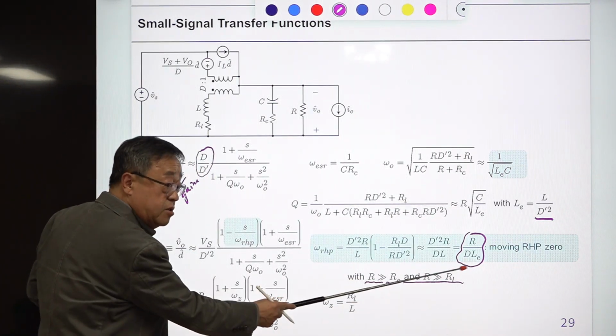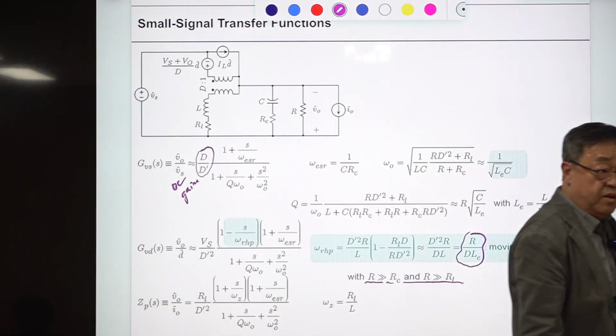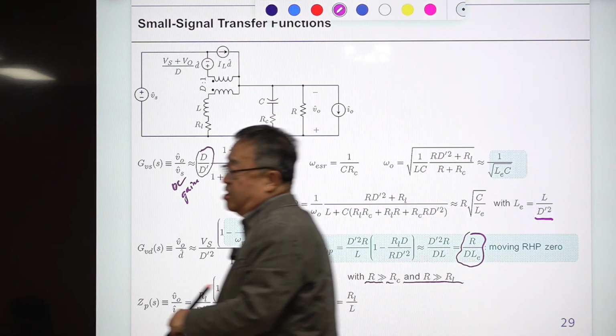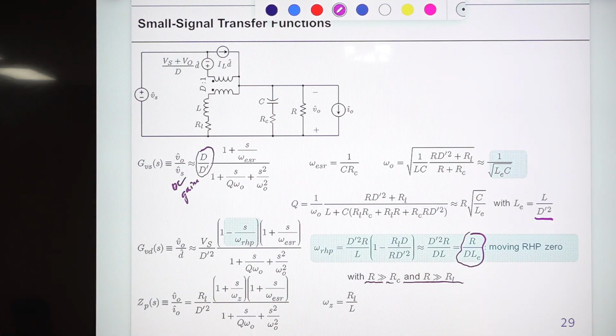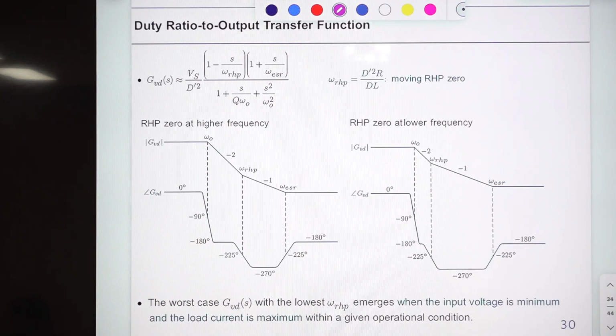Right, okay. So the worst case is low voltage, low line, heavy load. The same condition as the boost converter, maximum working condition. So input is small and output is large, so you should work harder. So it's the same case, so everything is the same. So this, you can move this faster, all right, same thing here.